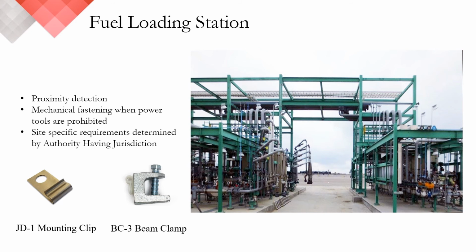In fact, the JD1 clip can be put on a stainless steel strap. The strap is by others, but we offer the clip. The stainless steel strap would go over the piping or the beam, whatever you are attaching to. The JD1 clip sits off the strap, and the Protectowire sits in the JD1 clip. So that would be another non-invasive way of being able to attach Protectowire all around this pipe puzzle fueling station. And now we can move on to our next tank.